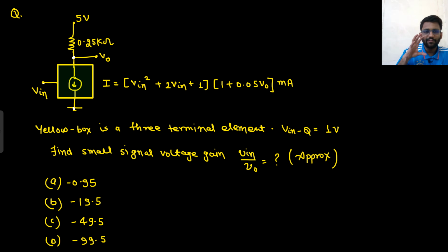So when we were studying amplifiers, when we started with the MOS amplifier, what was the scene? Can you relate this blue box with a MOS amplifier only, or MOSFET only? Input is applied, you are having the output, and there is a current. What is the current relation in that? For MOSFET, for MOS, what was the current relation? That was some Kn (VGS minus VT) into (1 plus lambda VDS).